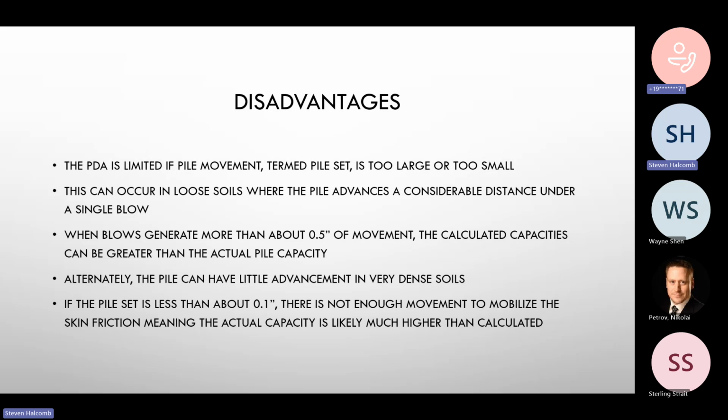So I think above 15 or 30 is where we'd like to see the blow counts. And if there are too few blows, a lot of times they can throttle down, just reduce the amount of fuel that goes into the hammer, so you get a lower stroke, so you're not hitting it as hard, and you can control blow count that way.